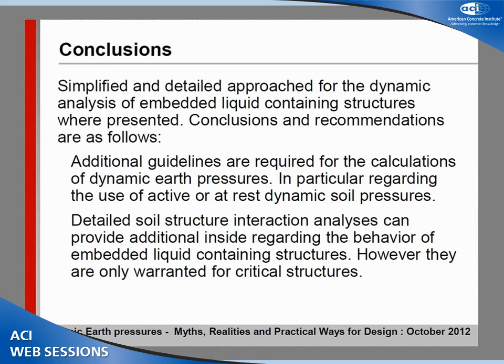Okay, so as you said earlier, the factor of safety is based on 1.0, not higher than 1.5. Yeah, just to verify there is no sliding, because of course we need to guarantee that. At least for nuclear structures under this very high seismic force, what they require is that it has to be larger than 1.1.